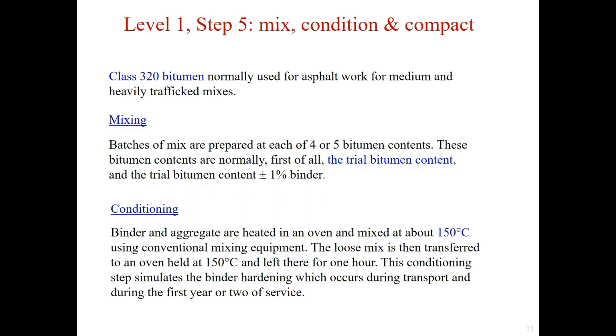The aggregate and binder are heated in an oven and mixed at 150 degrees. The mix is then transferred to an oven and conditioned under 150 degrees for 1 hour. It simulates the hardening of the binder during manufacture, placing of the mix, and initial service period. In such case, the prepared sample could reflect the real behavior of the filled pavement.